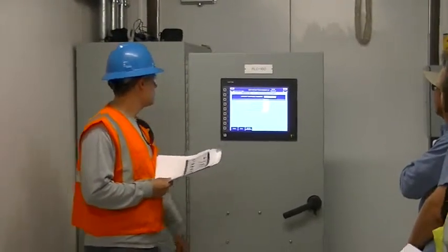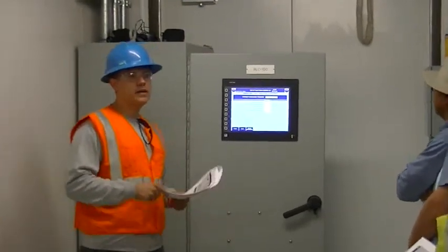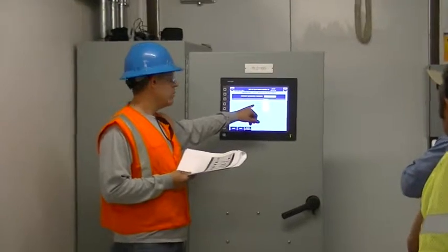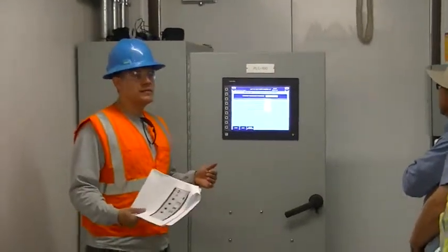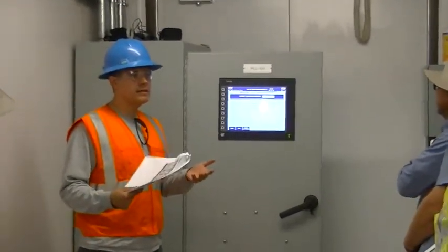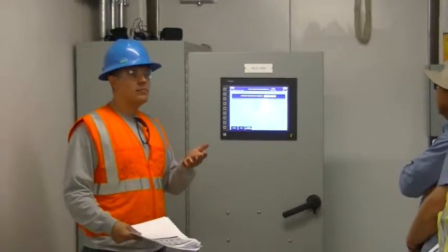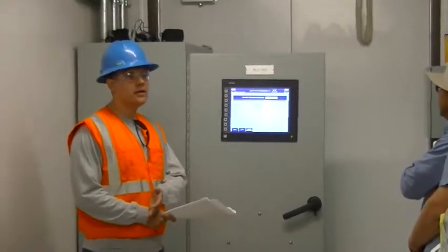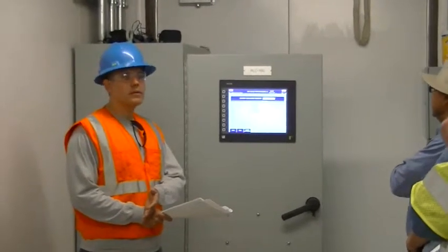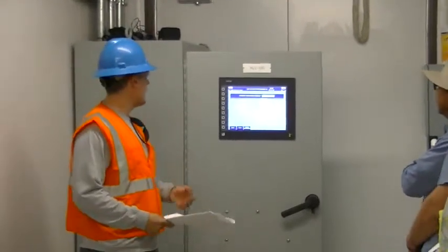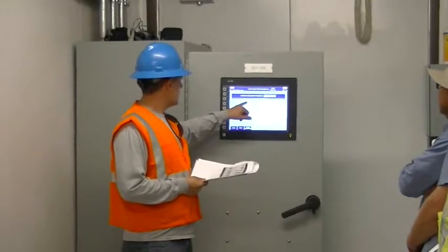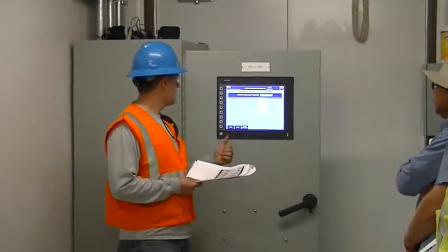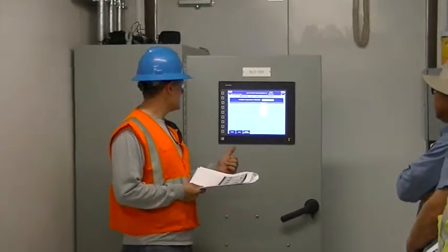So the emergency duty set points are for the RVSs, the soft starters, the big pumps. They run in a lead-standby setup, so both of them aren't going to come on at the same time, just one at a time. If one fails or shuts down, they'll alternate depending on your run-time hours or which was on last. So your lead start pressure set point: they'll start up at 50 and they'll stop at 73.